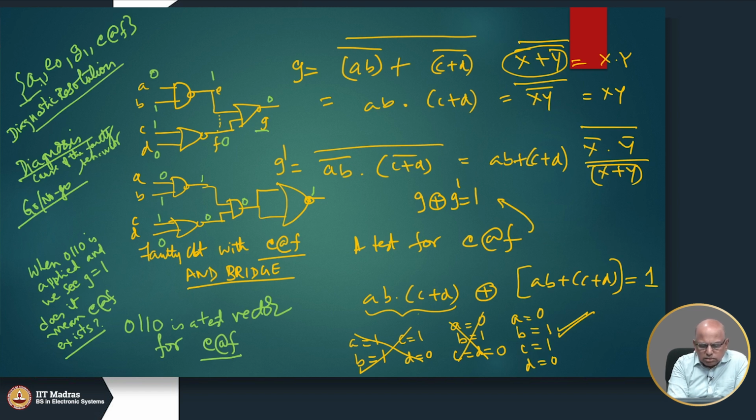Finally, when they really want to figure out what the problem is, they may use other methods. For example, using acids, you can expose the layout of the circuit, photograph it, and then actually see whether the defect is in the bridge fault, etc. Those are techniques that people use at a much later stage.